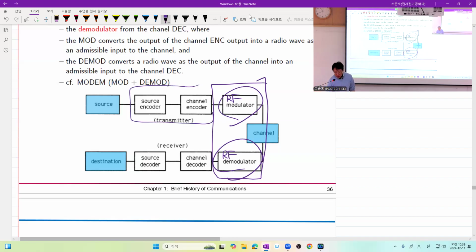And here is something interesting. Before, we didn't separate source encoding and channel encoding. But under certain conditions, we can separate the encoder block into a source encoder that only looks at how we can compress the source signal. So we compress the source signal as well as possible using the source encoder. The interesting result is that if we remove all the redundancy, so we maximally compress some signal, then when the signal is represented by bits, the mathematical theory says that these bits look like IID bits with probability 0.5. So it looks like independent IID bits.